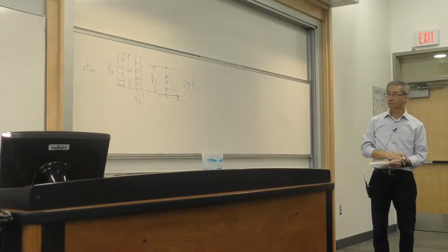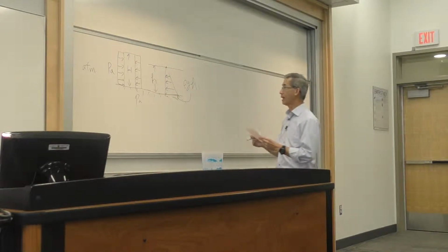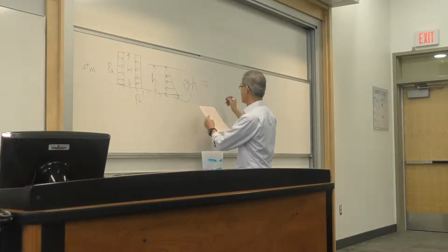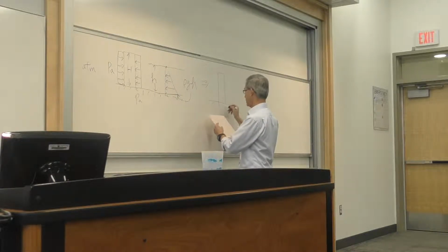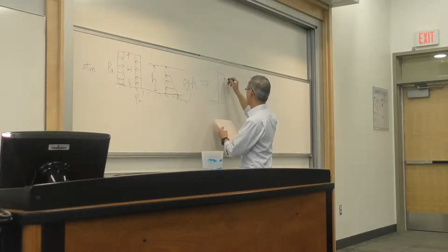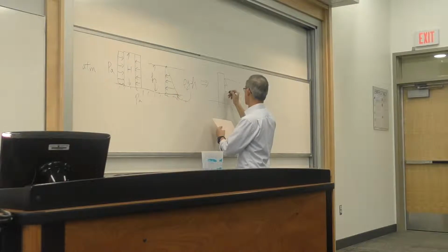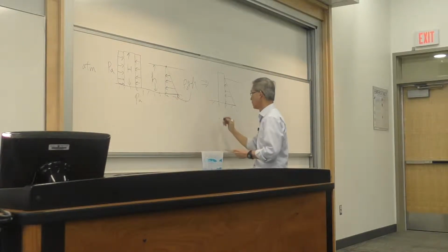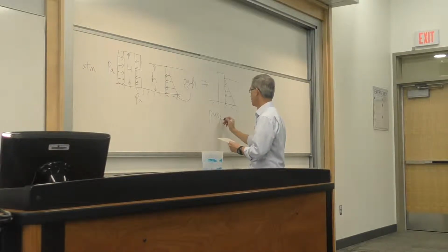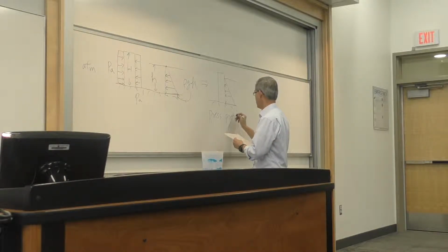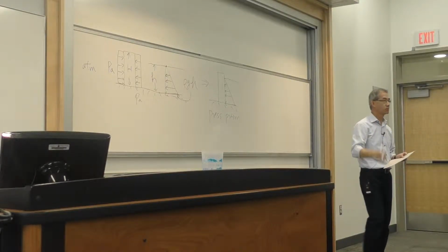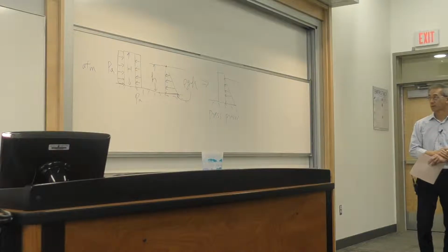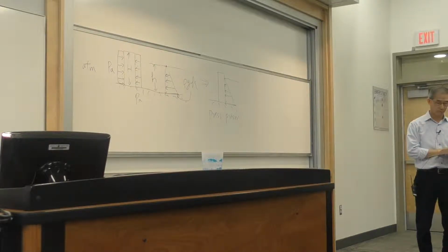So from this diagram, the net forces due to water on the dam. Now, after we go through that argument, it's nothing but a prism, which I call the pressure prism, a triangular shape. Zero at the top, rho gh at the bottom.